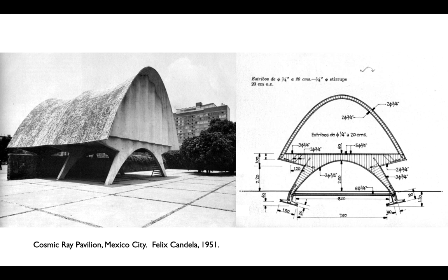and drapes it over this parabolic or catenary shape. You can see if you look closely, it's got a positive curve in one direction and negative curve in the other. We will talk a lot about this when we start talking about shells. But if you look even more closely, what you see is that this is actually a very, very tiny building. It's only about 25 feet across. Is that a long span? Well, quantitatively, no, it's not a long span. It's a relatively short span.